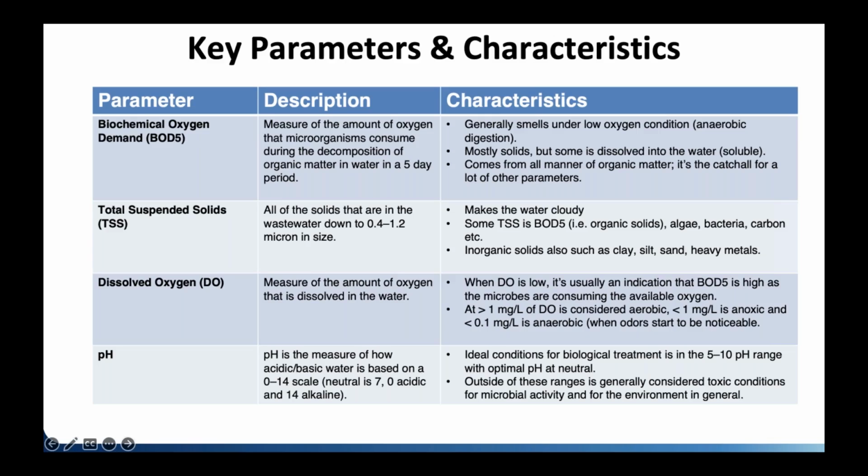And then they're basically cooking that filter to boil off all the water, and then they're seeing how many solids are suspended in the water column. So it's a measurement of mass. And some of that solid is BOD, some of that solid can be sand and grit and inorganic materials that find their way into the wastewater. It's really a grab bag depending on your type of wastewater, but that's all it is. It's the amount of solids that are in the water.